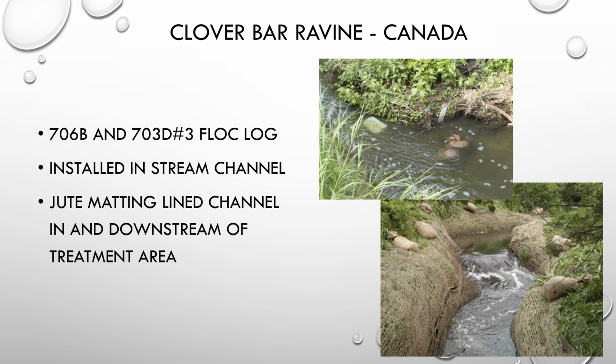In this example, we put the flocculant directly into a natural stream. You should certainly check with your state or local regulations to make sure that you're using the flocculants in ways that are allowed in your area, and apply for any permits that you might need to put these in waters of the state. In this project specifically, we were using this directly in the stream with permission.